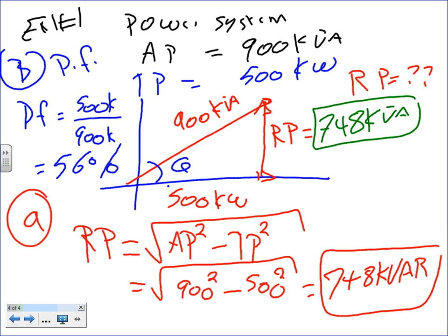Now, Mr. Bew, where the heck would you get these numbers? A building like Dunwoody, how would you know? This number is easy because you can measure the current and the voltage. Every one of us knows how to clamp on an ammeter and measure the current. Measure the voltage, multiply the current by the voltage, and because it's a three-phase, you multiply by 1.73, you get the 900.